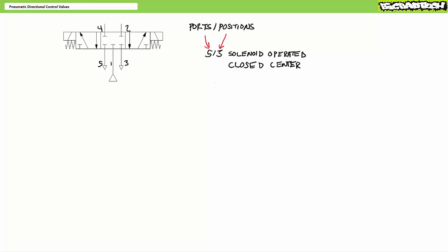Lastly, let's take a look at 3-position directional control valves. The previous example, featuring a 5x2 directional control valve controlling a double-acting pneumatic cylinder, was limited to 2 choices, either full extension or full retraction with no midpoint option. A 5x3 directional control valve allows this increased functionality. Consider a double solenoid actuated 5x3 directional control valve spring-centered to a closed position where all ports are blocked.